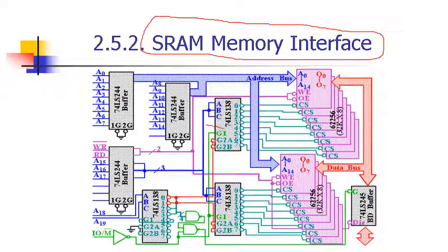One decoder to select among 8 different chips, let's say the highest addresses of your system, and another decoder to select among the lower 8 different chips. Okay, and we need an additional decoder to select one of your decoders, the upper one or the lower one.